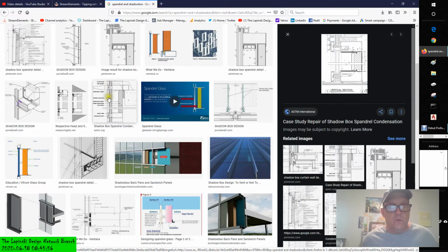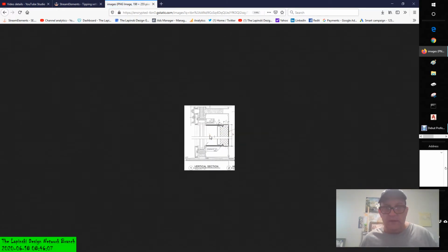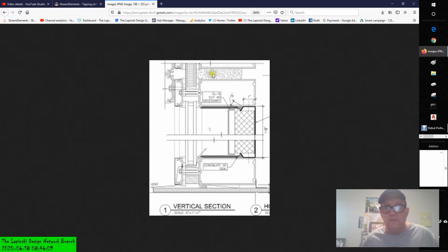Well, the wall and ceiling sandwich and the wall and floor sandwich are mirror images consisting of vertical components, different components. This is a bit pixelated, but it would encapsulate the wall ceiling and the wall floor sandwich. So I'll read it again. Often in glazing applications, the spacing of horizontal members will consist of a pattern, including a narrow band or spandrel, to mask the floor and ceiling sandwich.